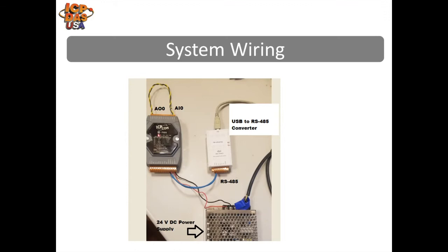The beautiful thing about RS-485 is you can daisy chain additional modules. So in other words, if you had, say, 3 M-7026 modules, you need to power each module, but you just connect the RS-485 wires in daisy chain format to two others, and you need to be sure to specify that each module on that bus has the same baud rate and parity options and different node IDs. I'll show you a screen capture of that afterwards.